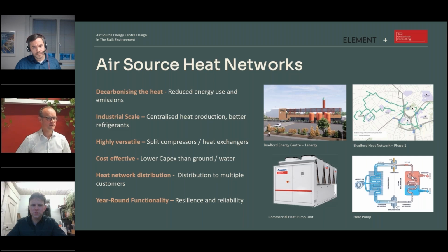So here in the UK, we have a large decarbonisation drive, spurred on by many things, political as well as financial. And decarbonising heat, which is roughly a third of the UK's carbon emissions, is a big part of the decarbonisation agenda. What we're looking at with air source heat networks is centralised heat production, which allows industrial scale production of heat, which gives access to things like better refrigerants and more economically sensible resilience approaches.